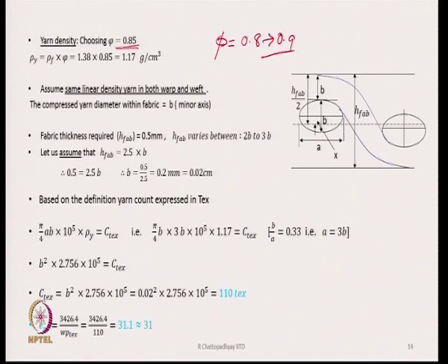Within the fabric, the yarns are locked in positions and there are pressures, therefore, they are highly compact. So, packing coefficient is very high. These are all filament yarns. A spun yarn's packing coefficient cannot be 0.8, it will be much less. So, anyway, we are choosing a value in between, which is 0.85.